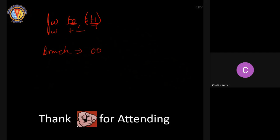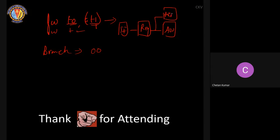Okay, so the ALU will still be needed. Why will the ALU be needed? Because there are still R-type instructions to handle, right? So here, you will have instruction fetch, then you will have a register file. In the earlier data path, you had an ALU. The ALU was being used for address calculation, hence the memory stage used to come after the ALU. But here the memory stage can come in parallel, and based on this, you can decide what to write. So your mem2reg mux will come here. Okay, so this is how the data path would look.